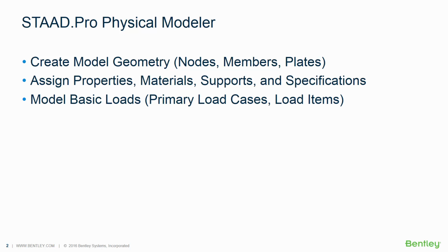Now, the physical workflow will be used to model your structure in the STAAD.Pro Physical Modeler using physical members. The physical modeler is used to draw structural elements as they are physically constructed. The program will then decompose this into an analytical model, which is passed to the STAAD.Pro Analysis and Design engine when you run your model. If you're planning on using the STAAD.Pro Physical Modeler in your workflow, it's important to know what tasks will get accomplished in the STAAD.Pro Physical Modeler versus the Analytical Modeler.